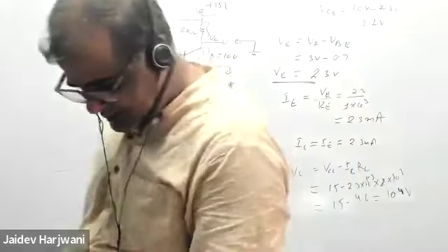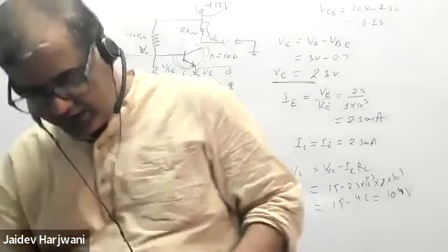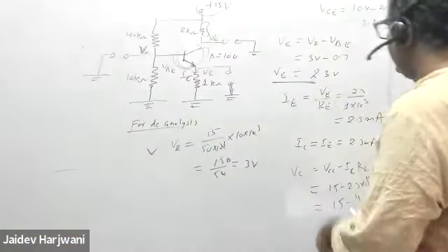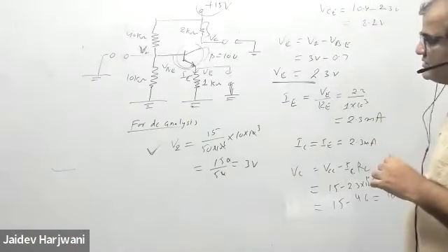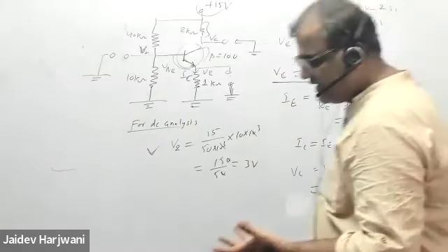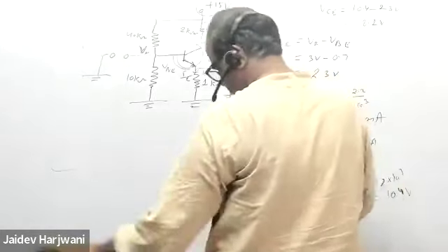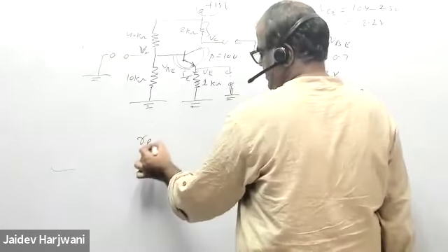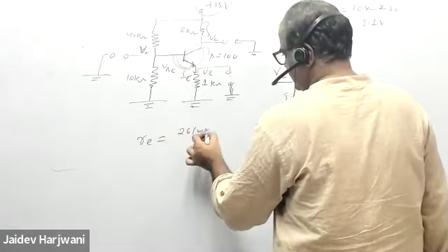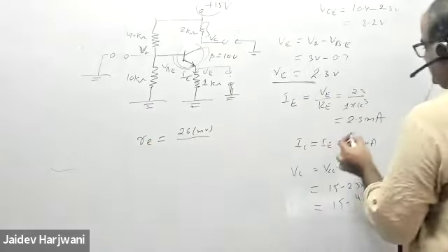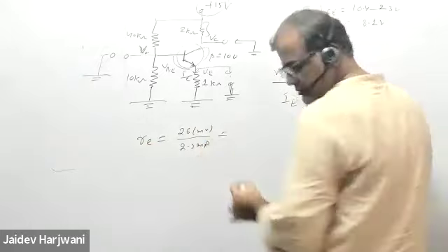And sir, bias level means we have to find the voltage across R1. DC bias means finally you want to find this IC, IE. The whole DC analysis. Because our purpose is to find RE. Now what is RE? We have IE, so 26 by IE. 26 millivolt by IE, which is 2.3 milliamps.